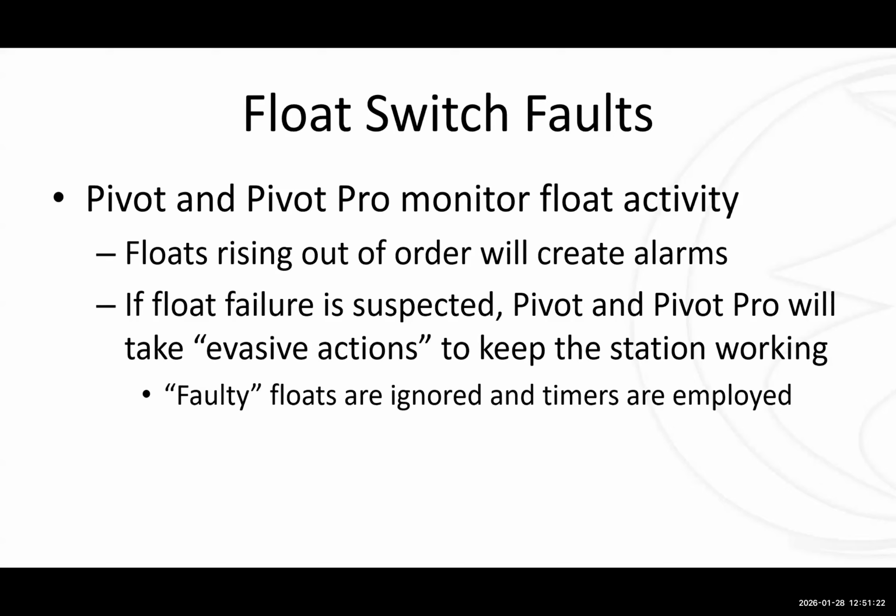It's going to start the pump, and it's going to run that pump until that middle float, that start float, drops out. But it won't shut that pump off immediately because it knows there's supposed to be some extra distance between that and the low float. So it doesn't just stop when that middle float drops out. It will run that pump for another roughly 10 seconds. It's just trying to lower that water a little bit more. It also keeps that pump from short cycling. And again, the goal is to keep the pump in that basin at an appropriate level. And there's an alarm going off too because it says, "Hey, something's not right here."